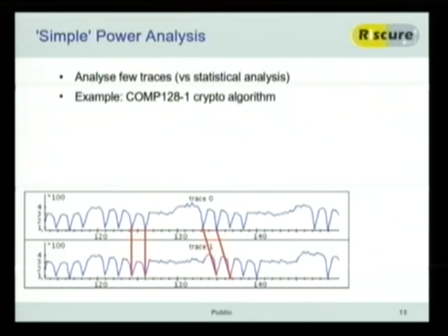Now, in this case, we had the source code of this algorithm. And we found in the C source code that a byte was being taken from a table of 512 entries. And this depended on 2 other bytes, so K and D. And K is actually the secret key that's being used, so that's the thing we're after. And D was just input data, so that's stuff we controlled, stuff that we could send out to the card. But why the hell would a table lookup, which we matched up to this part, be non-constant? It's just a memory indexing.